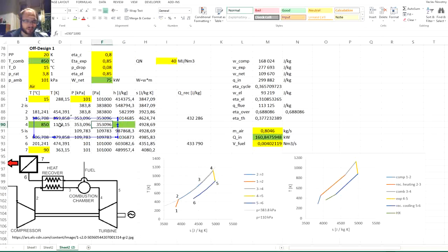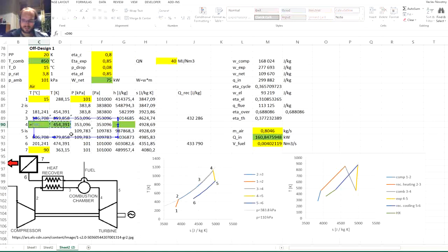But now we have specified enthalpy in here. We have the pressure, so the temperature can be a function of enthalpy and this pressure. Let's borrow the function for it, for example, from here. So another cell that we changed, and this one, temperature in degrees C, will be just temperature in Kelvin minus 273.15. Yeah.